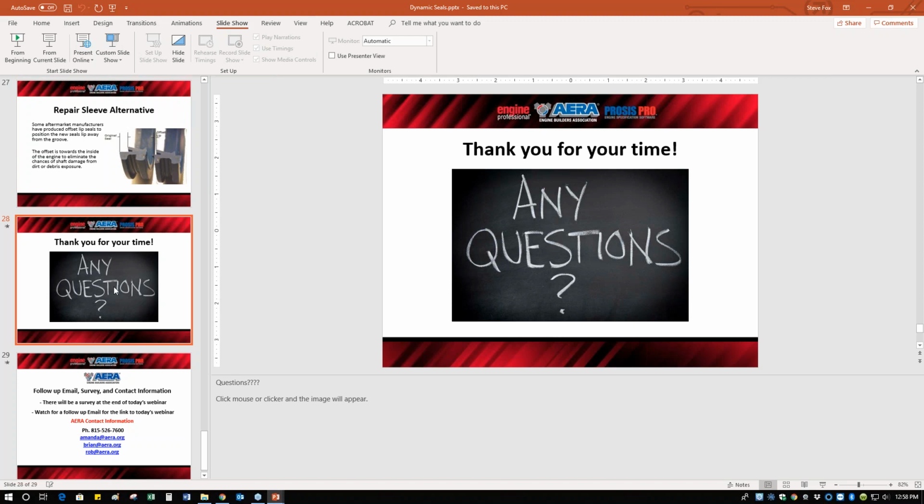Another question: can you reuse a dynamic seal if they've only been in for a short period of time? I would say I would not recommend doing that. I mean, what's a short amount of time? Who determines what a short amount of time is?